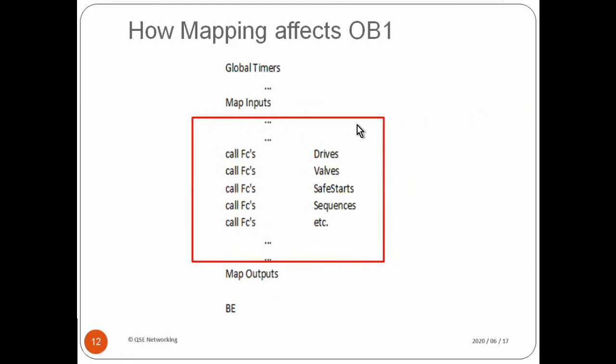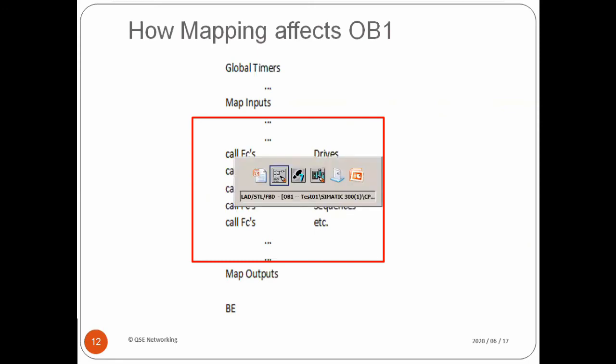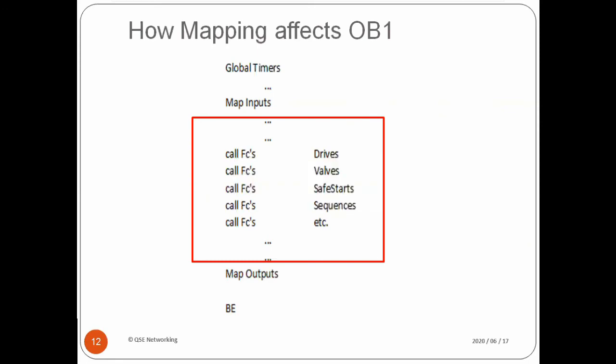So just a reminder, everywhere in this part of the OB1, all those functions, all those blocks do not reference physical I/O at all, which makes your life simple, because if you have any problems, you just do it either in the inputs or the outputs, and you can do your rewire. You can even force it in there. Now, I have had lots of bad experience of forcing, so we will actually talk about that a little bit later, that we will not do forcing.